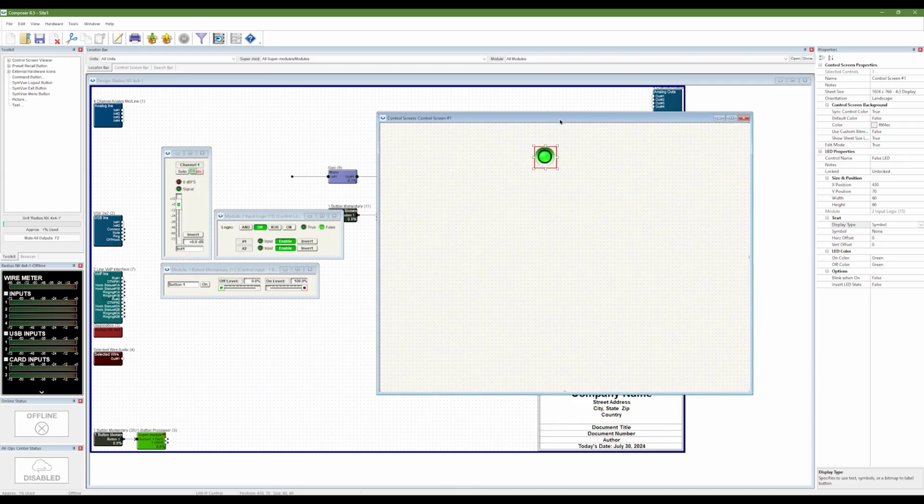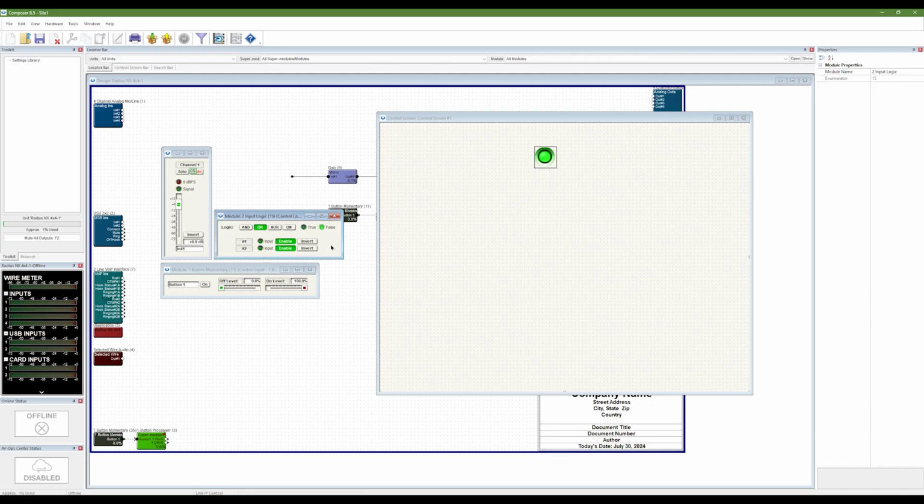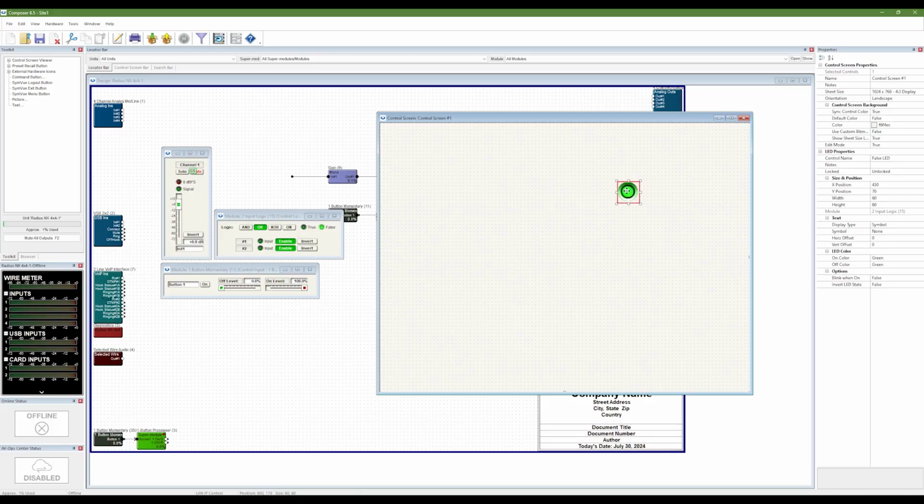Because the mute button takes its cue from the on button, when the on button is active, it makes the logic module true. If we wanted to use the true state LED for the indicator, we would need to change the logic inputs to invert. We could be finished here if we put this LED next to a fader control or only needed a light indication. We can, however, go a step further and offer some label indication as well.